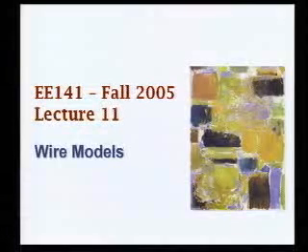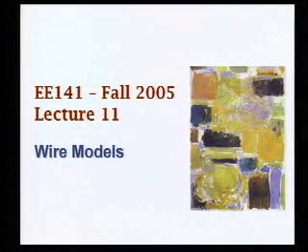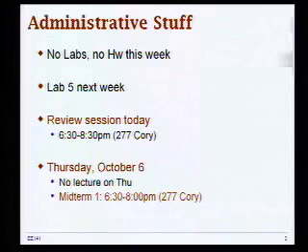So what we're going to do today is continue with introduction to wires and expand our discussion from last time onto transmission lines and inductive effects. What happens when you operate at ultra high frequencies, when you need to worry about inductance as well, and then we'll try to understand how to include that into our analysis. So we'll then devise electrical models for analysis of this behavior and do a couple of examples.